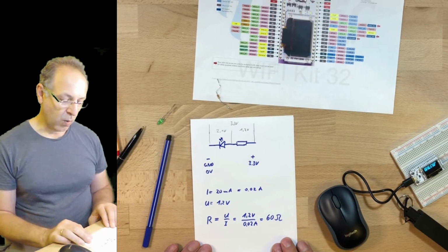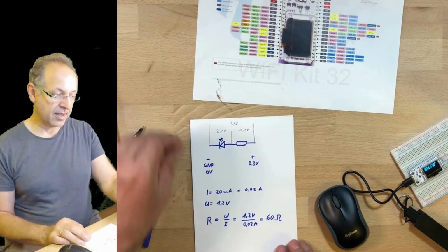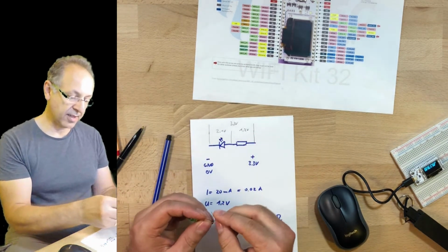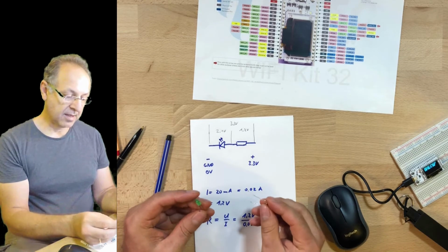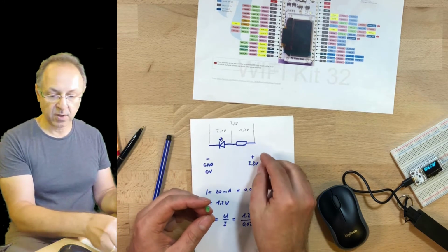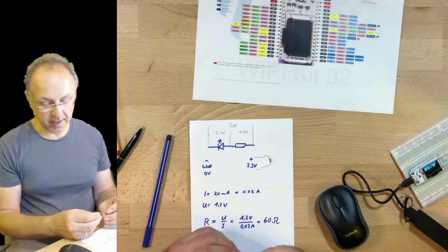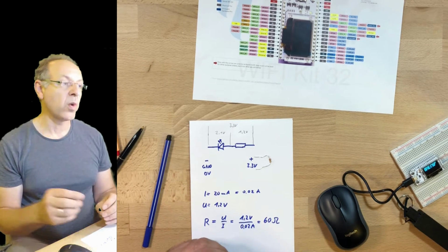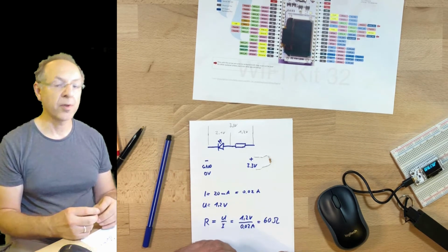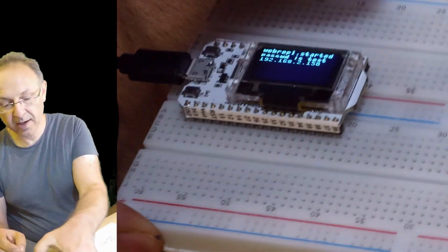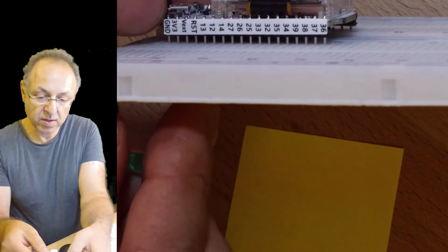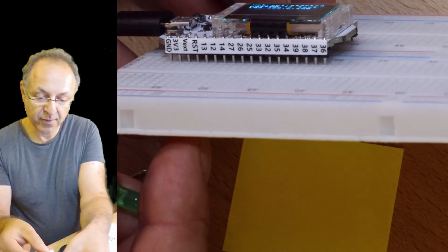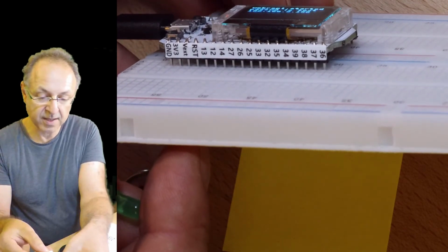So now what do we have? We have an LED, and I already have a resistor that's fitting. Now let's have a look if we can connect it. I'm not programming the microcontroller yet. I'm connecting it to where we have 3.3 volt all the time. So if we look here, it shows what pins we have, and the first pin is ground and the second pin is 3.3 volts.